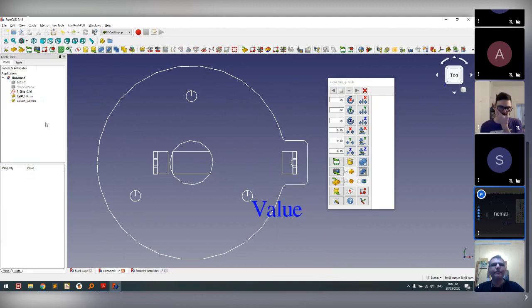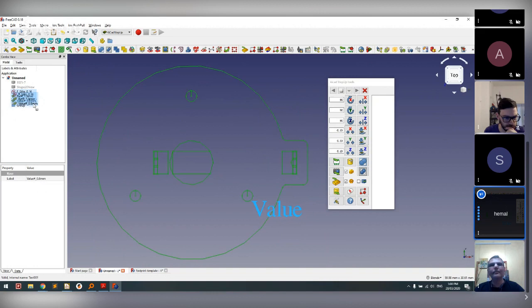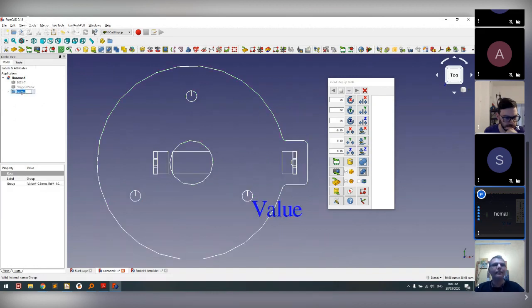Once you have these three pieces of information, you click over here and create a new group for ordering objects. It basically creates a subfolder, and you have to move all three objects into this group. You can rename this group, usually to the name of the footprint.